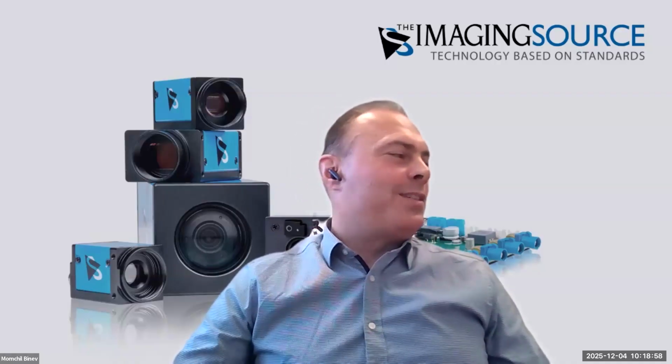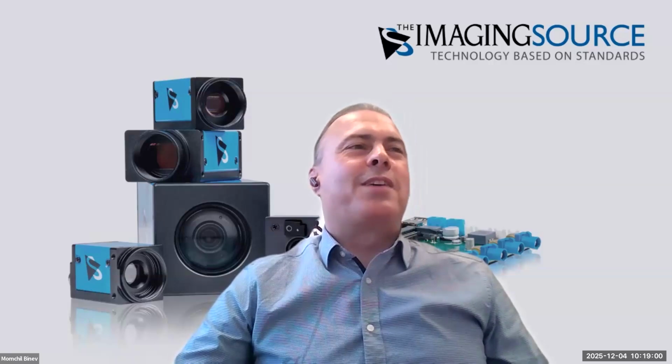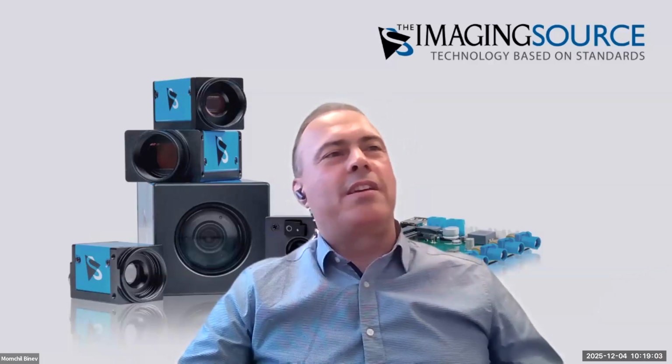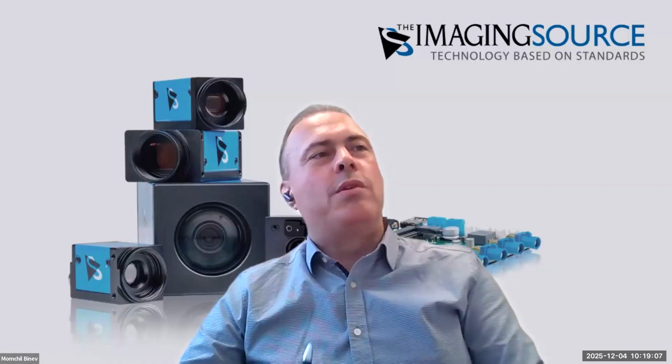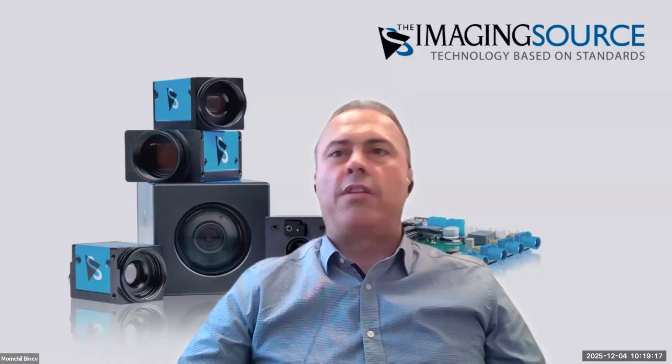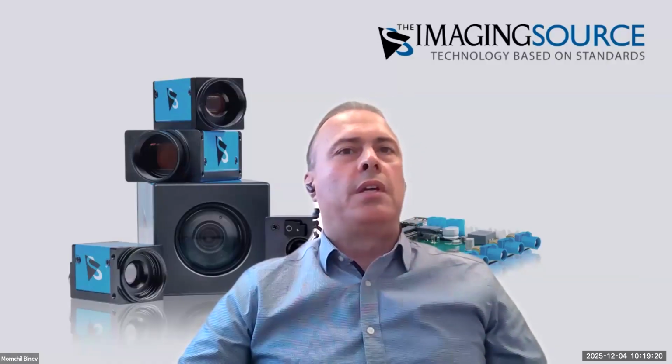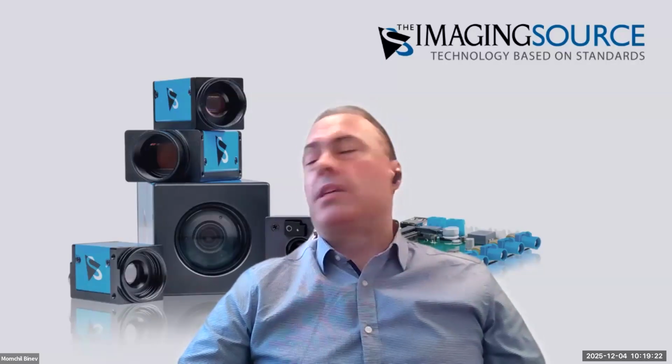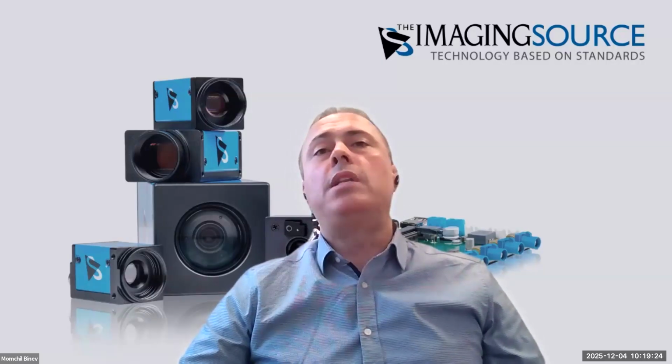They work reliably, and the glass-to-glass latency is very interesting, because glass-to-glass means from the camera taking an image, going through the complete pipeline on the GPU, and actually displaying the image on a monitor. And of course, the monitors also introduce some latency. But it's interesting. This year we had a project with FPD-Link cameras, and we measured a glass-to-glass latency of 60 milliseconds.